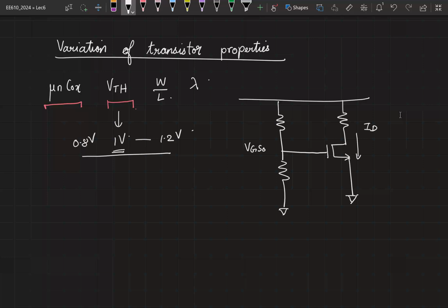Now, if the new VTH of the transistor has a small variation from the expected VTH, let's say it is the original VTH that you thought it had plus some delta VTH, what happens to the current? The current changes, right? Which would mean your operating point has changed, your GM has changed, swing limit calculation has changed, everything has changed. How do we proceed now?